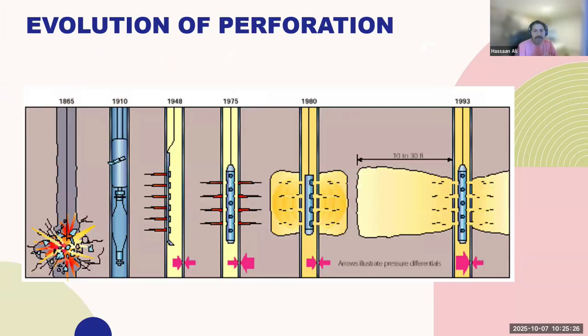Let's talk about perforation. So what is perforation? Perforation is a process of creating a channel of communication between the wellbore and the reservoir. This should be achieved without damaging the inflow ability of the surrounding formation, to ensure that the perforations do not form a restriction on the production capability of the completion system. There are generally different types of perforating options available for most completion applications. Selection of the most appropriate technique will consider specification of completions, for example the dimensions, the reservoir conditions, and local experience.